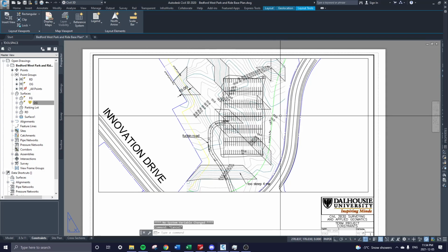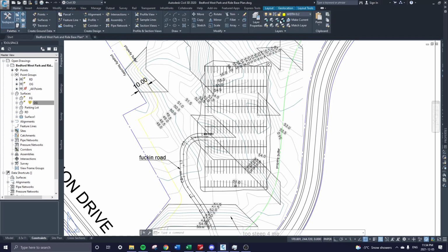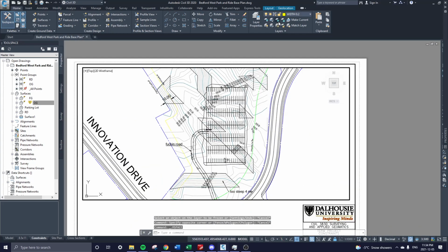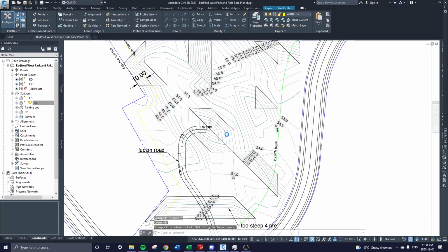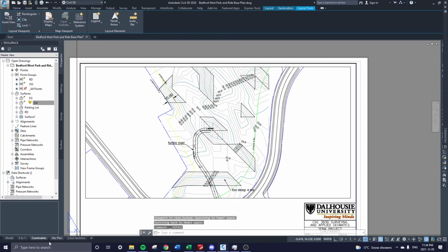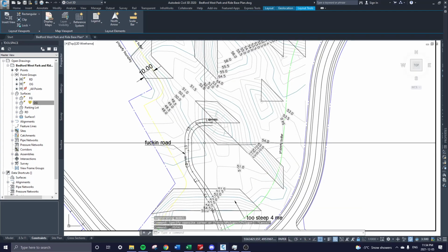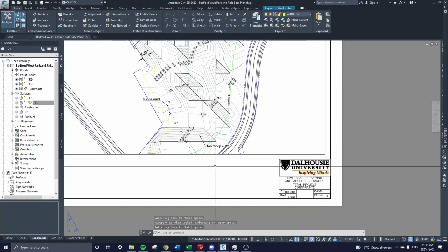So, okay, how do you get rid of the stuff while still keeping it? Nice little thing. You can freeze layers. This snowflake. Just click that guy, and you can just. Oops, is that not selecting? Okay, maybe you have to go within, and that's just going to freeze stuff. See, but if we go back, hey, still there. Don't worry. It's just another filter. You can filter things that you don't need, etc., etc.